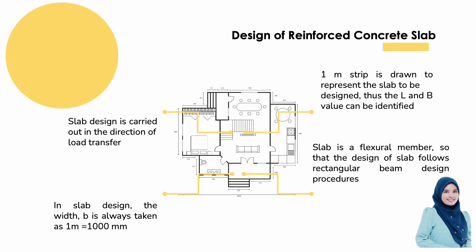As an engineer, you must consider factors such as the variable action, the permanent action, the serviceability criteria, the deflection limit, and the reinforcement design based on the moment and also the shear calculation. Additionally, the local building codes and design standards may dictate specific design procedures and load combinations that must be followed to ensure the safety and stability of the structure.